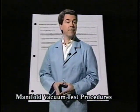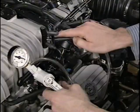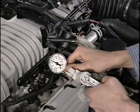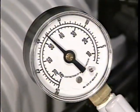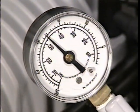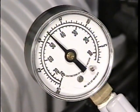For example, manifold vacuum test procedures and results are explained. You should connect the vacuum gauge to a suitable manifold vacuum source. Then, with the engine running at normal operating temperature and the transmission in drive, you should see a steady vacuum reading between 16 and 22 inches of mercury.